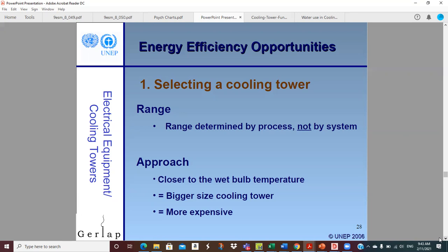Well, the standard design condition on a lot of HVAC towers is 85. So if you were specing a tower for that, you probably have to upsize it for a given flow rate so that in your hot weather, you could achieve an 80-degree leaving water temperature to keep that furnace happy.